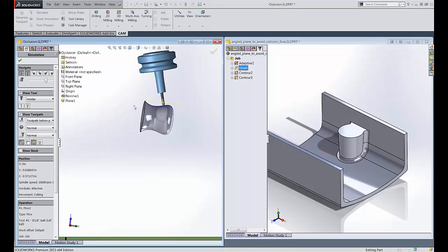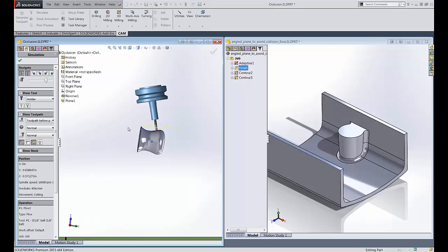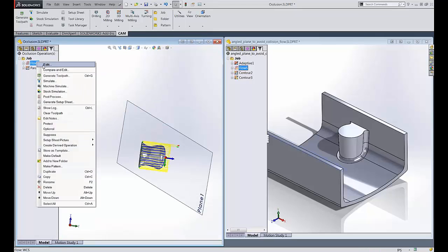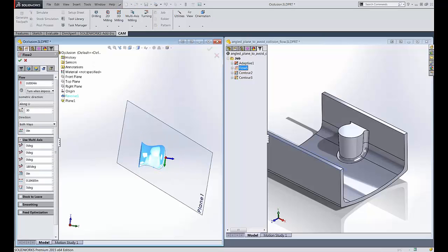That's probably within what I think most 5-axis machines will give you, about negative 100 degrees or so. I think 120 is about the max I've seen. And that's because your table starts getting in the way, and we'll look at that when we get to some stuff that has a vise and some machine simulation. You just really don't want it tilting that far, but you do need to control the tilt so that it can get past and access that occlusion. So that's where controlling the maximum amount of tilt is really important.